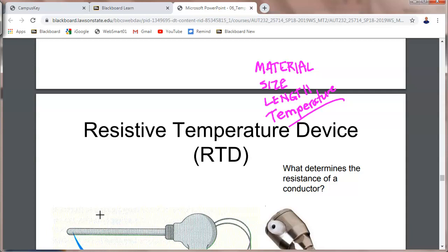Now, every conductor has an R. If you put I through an R, you get heat. If you put an insulator around it, then the wire cannot dissipate the heat as fast, and its resistance changes. So if you looked up how much a 14 gauge wire could handle at 25 degrees centigrade, uninsulated copper wire, that sucker can handle 30 amps.